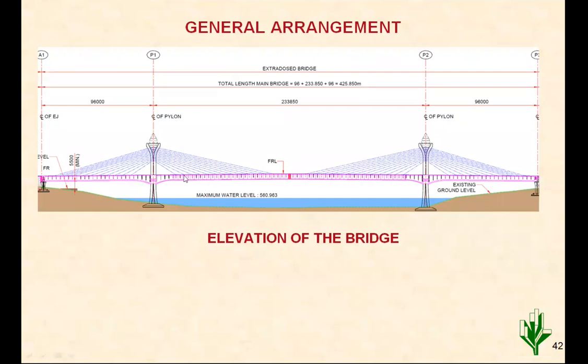So the consumption of these external cables, which are very costly because they are imported, becomes less. So this kind of structure becomes cheaper, but then you will find that the depth of superstructure is more, which is not feasible in case of a railway line crossing or so. Otherwise, it requires longer approach spans. So considering the economy and the constraints, we can plan either an extradosed bridge or a cable-stayed bridge.